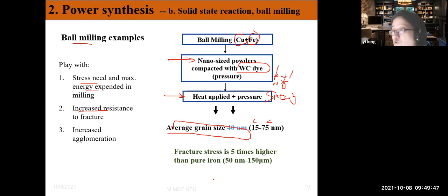But the pure iron at the very beginning, when you put it inside the ball mill, is actually 50 nanometer to 100 micron. So you can say it's a very large variation of the particle size. That is very often. Okay, so you intrinsically will know, right? If you want anything uniform or very much controlled, your starting powders have to be very uniform and well controlled. Am I correct?